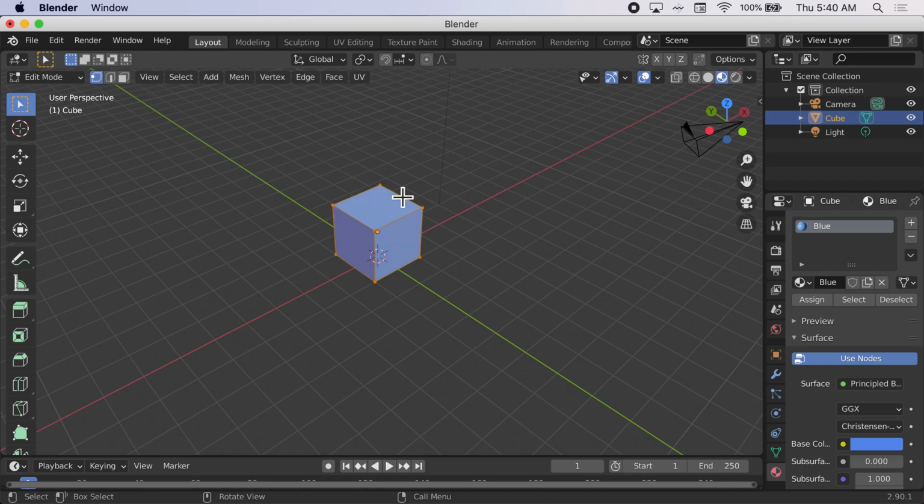So I'm going to open up the ring cut tool by pressing Control R. It defaults to just 1 ring cut, as you can see right there. I'm going to press 2 because I want 2 ring cuts, and I'm going to hit Enter. Now if I move the cursor around, I can actually move those ring cuts back and forth if I want to. So that gives you the option. You're in the mode right now where if you want to start moving those ring cuts around, you can, and you can start doing some other things as well.